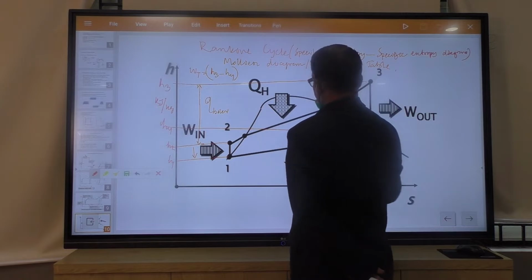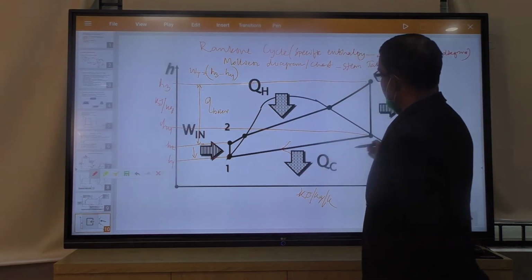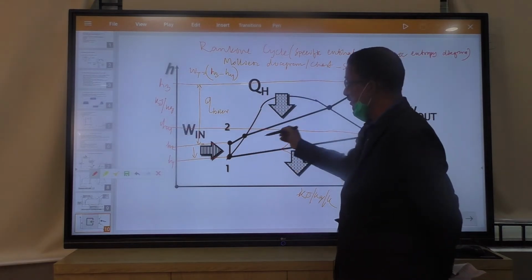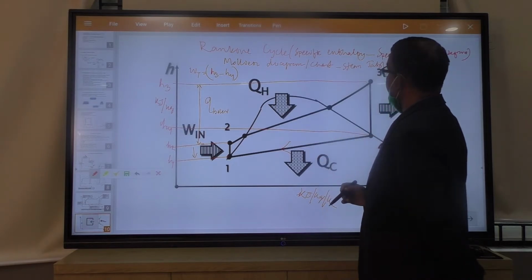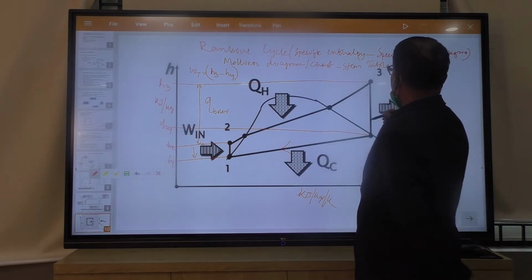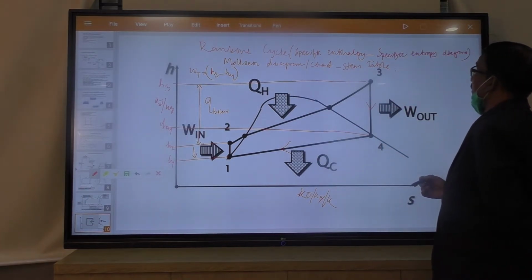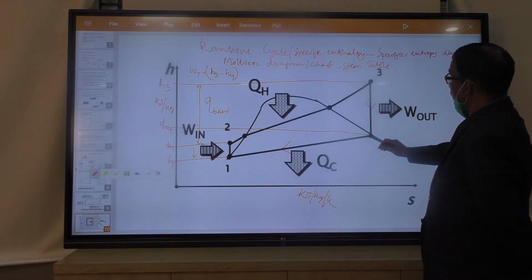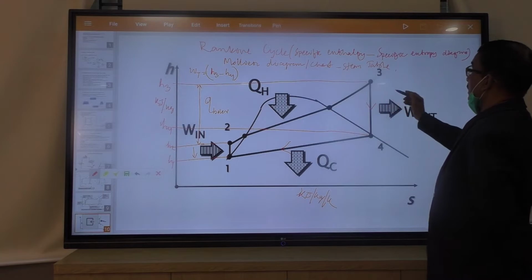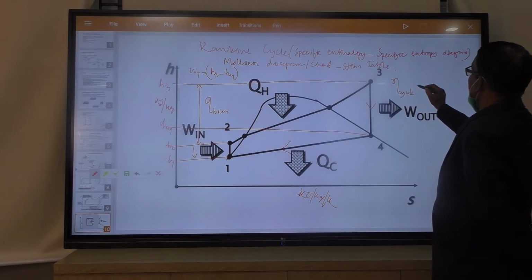So it is a downward line, this process direction is forward but it is inclined downwards. So that means heat rejection takes place. And here you know turbine is always an isentropic process, reversible adiabatic process. So work done is this difference, H3 minus H4. You can get it directly. So you can get the efficiency of the plant or cycle as the net work done.